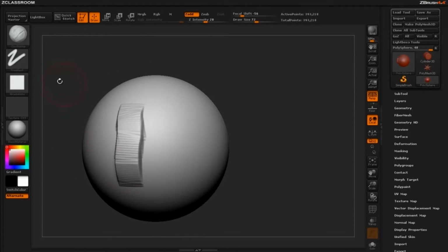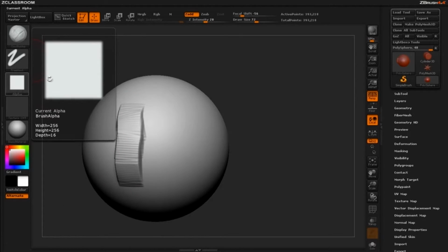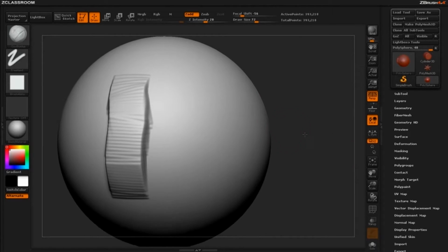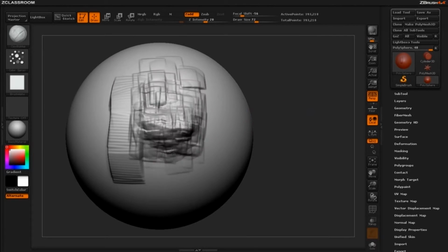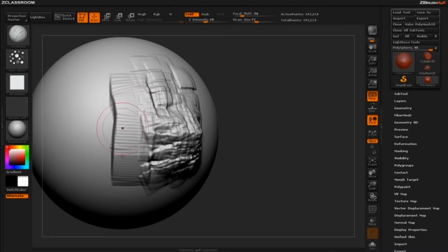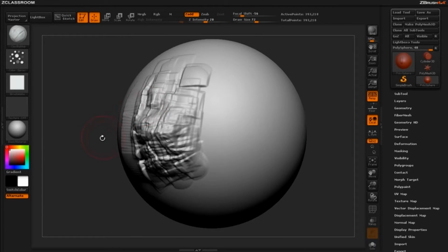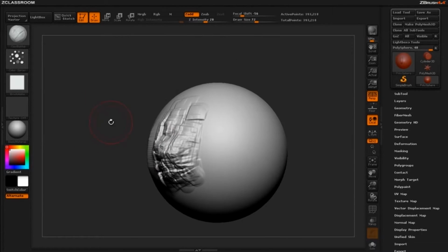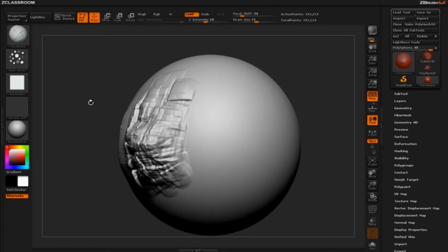In our first example, we'll start out with a clay buildup brush, which by default has the settings just mentioned, and manipulate what the visual representation of your movements across the mesh will be by simply changing the stroke type. Here, you see the visual effect of the default settings. When we change the stroke type to color spray, for instance, you can see the visual representation of that kind of stroke being quite different from the standard stroke type.